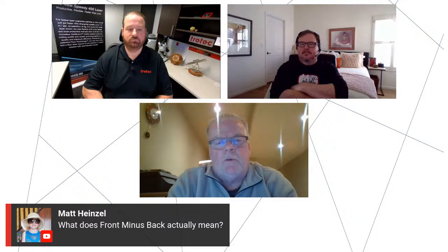Thank you. So we were just discussing some of these different features in CorelDRAW and answering some of these questions. Feel free to chime in on this one. A customer is asking, what does front minus back actually mean? Well, it's basically looking at the stacking order, is what it's referred to. The way we draw a rectangle on the page, you then draw an ellipse. Your ellipse is going to be above that in the object manager, or the object docker rather. And so you're removing the front portion from the back object is what you're doing.